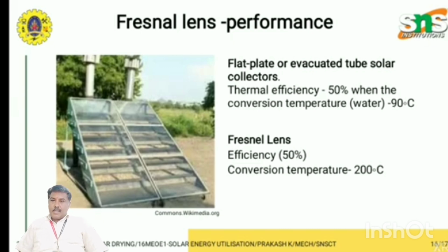Here this is a simple solar dryer where you can see that the drying materials are kept in trays at 45 degrees. Why is it kept at 45 degrees? We are keeping it like this to get most of the direct radiation, the radiation without any disturbance falling on the earth surface has to be trapped, so it is kept at 45 degrees. In India most of the solar collectors are kept in the south facing direction.